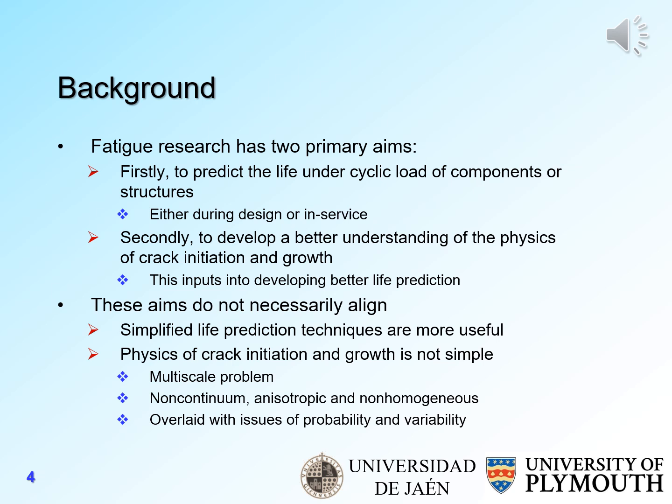I think the fatigue research has two primary aims. Firstly, to predict life under cyclic loading of components or structures, and this can occur either during design or in service when you're involved in condition monitoring. And secondly, to develop a better understanding of the physics of crack initiation and growth, which will of course input into developing better life prediction.